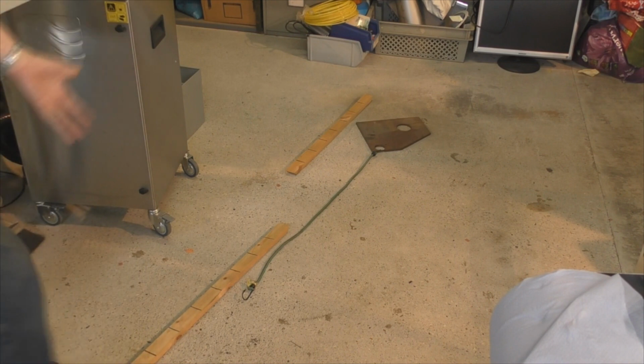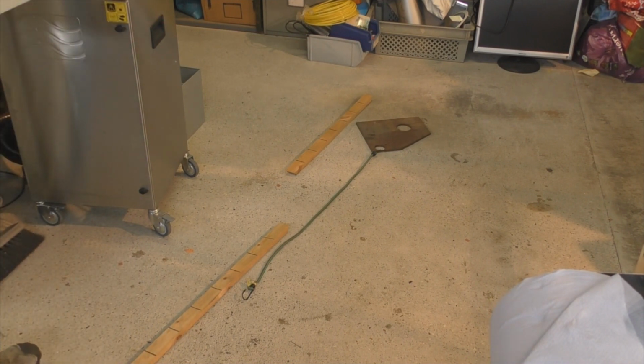How can we improve the performance of this system? This is a stepper motor system and there is no feedback. The control system says, I want you to move 5 steps. I moved 5 steps, but the load didn't move 5 steps, it only moved 2 3/4. And the load doesn't know that it hasn't moved 5 steps.